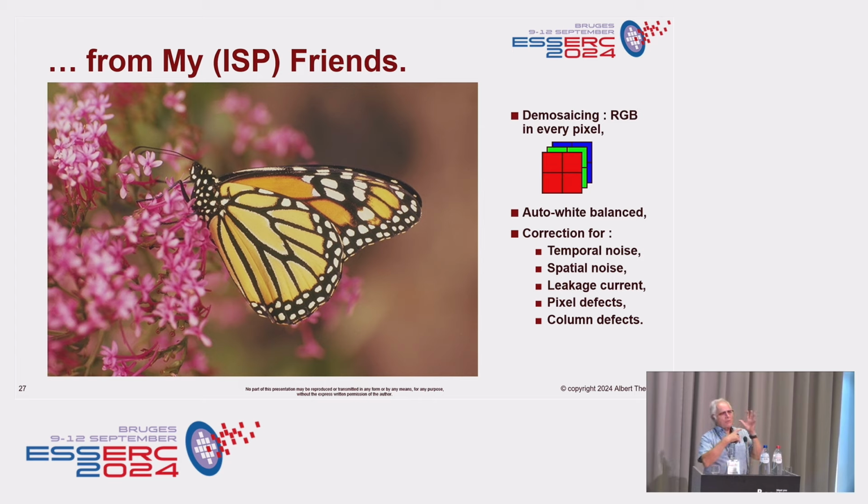Because as soon as you switch on the camera, the camera starts grabbing images. And it stores them in a memory, first in, first out. And basically, at the moment that you hit the red button, it retrieves the last eight images and simply averages them to get rid of the noise, or to reduce the temporal noise. All that kind of tricks are being applied in a mobile phone. But if you look at an image sensor or a camera for machine vision, then you apply other tricks and so on and so forth.